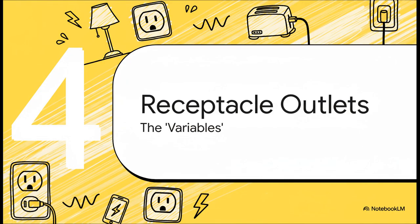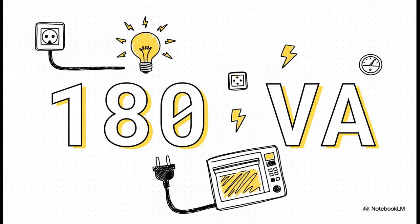Okay, so we've covered the knowns and the lights. Now for the last and honestly the most common tool you'll ever use from this toolbox, the everyday receptacle outlet, the variables. Since you can't possibly know what someone's going to plug in, the code gives us very specific default values to use. Seriously, if you remember one thing from our chat today, make it this number, 180 VA. This value is the absolute cornerstone for calculating general use receptacle loads. Let's see how it works.